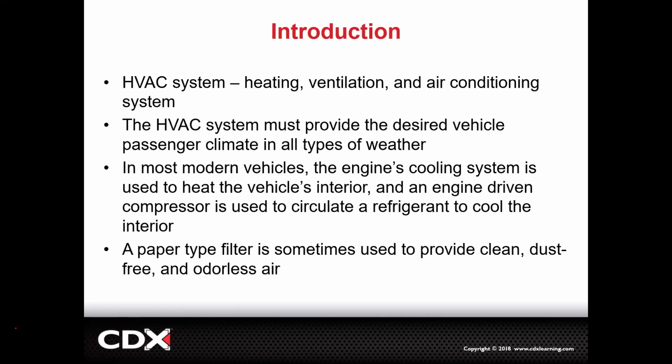Typically in a modern vehicle, the engine's cooling system is used to heat the vehicle interior. If we have a car with a no heat concern, and we will spend a day on heating systems, it's not that complicated. AC, we're going to spend a few weeks on. The heating system, from the perspective of HVAC, is to make the air warm. It's the same parts as the cooling system for the engine. We're just looking at the opposite side of the same coin. If you have an engine that's overheating, maybe it's a fan, maybe it's a radiator, maybe it's a coolant leak.